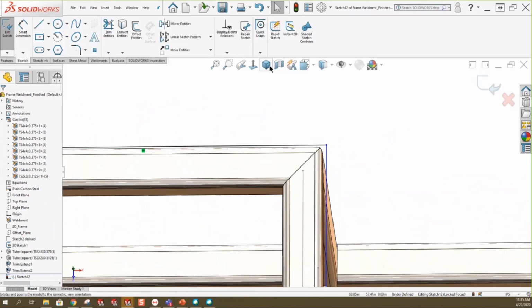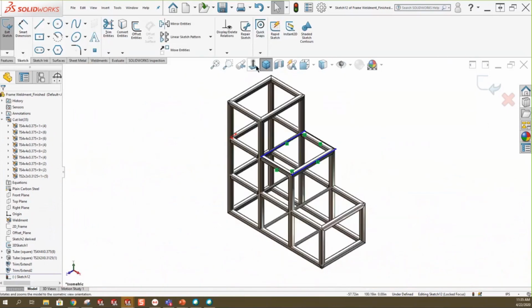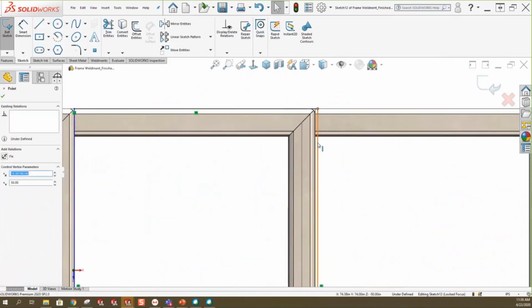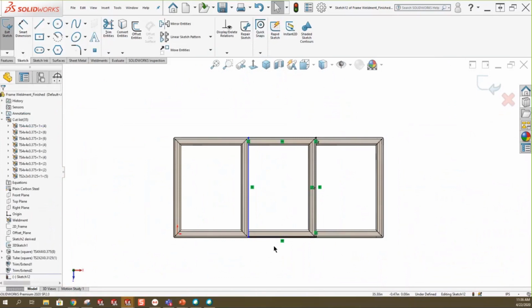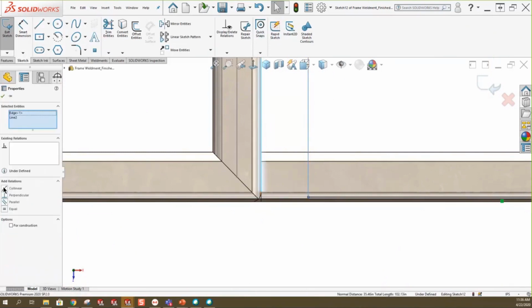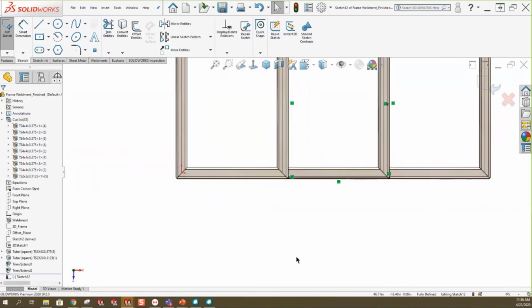I might turn around and say, let's go to a normal 2 for a moment here. I might go ahead and say, you know what, that point I'm holding, control, needs to be coincident to this edge right here. And make it coincident. And then you can see how that's starting to lock things down, right? And you can see this one moves. Maybe I'm going to pick that edge, pick a line, and say you two are collinear to each other, whatever it might be.